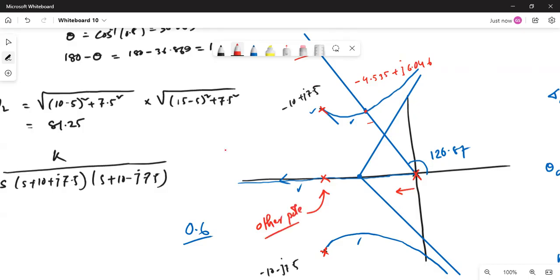Now you have to find out all the lengths. Approximately say this is your x, location is x, and this is one of the original poles, and the other original pole is this. So you have to find out the distance from each. All the pole lengths, 3 pole lengths, have to multiply to equal your 624.3.